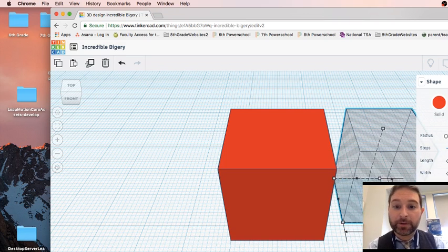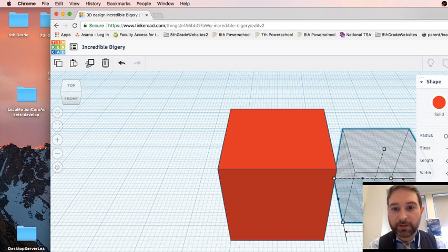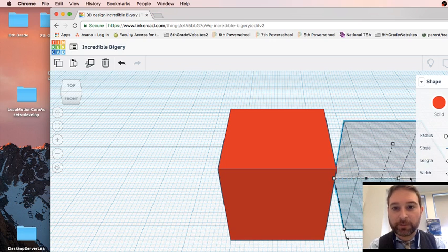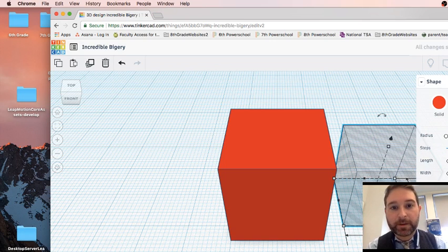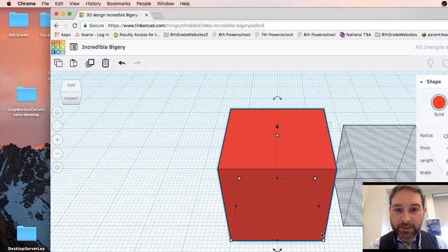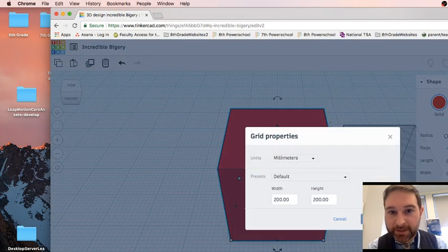Okay, both are useful. So if I hold down Control and Shift, though, that's kind of what I was hoping for. So the box itself, we can look and see, was 20 by 20, and that's in millimeters. And we can snap to grid. We want that on.